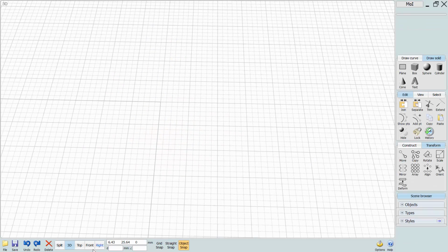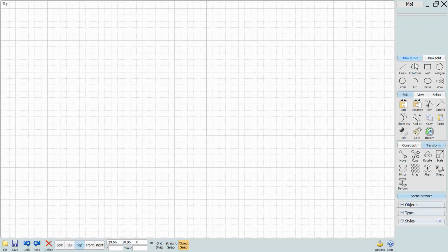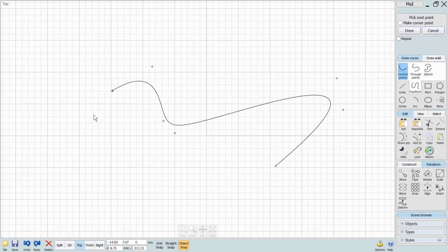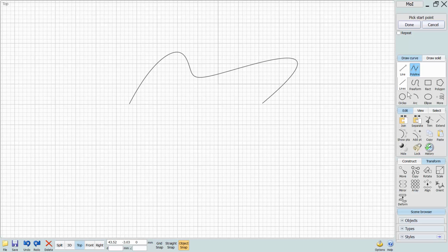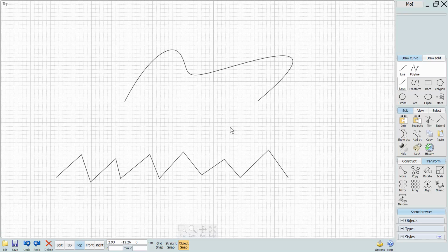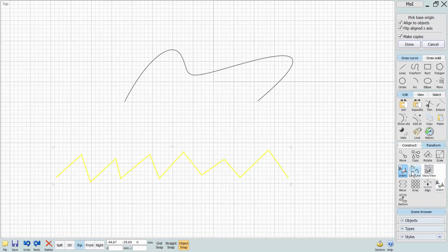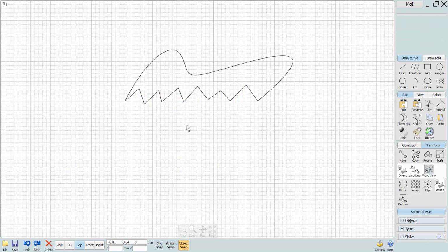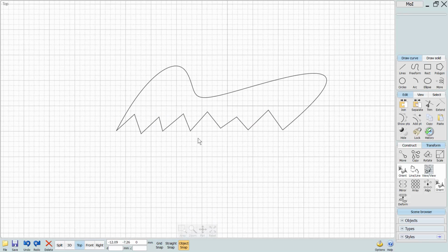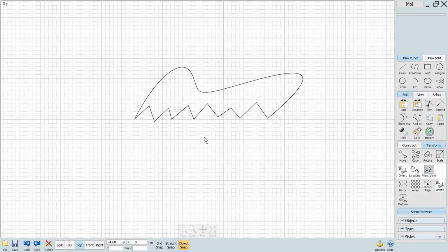With the second one, which is called line, you can orient your elements between 2 points. So let's say you have this curve here, and I want to use one polyline like this. So if you want to fill this gap between this and this endpoint with this polyline, you can select it and then go to orient, and then you can use this line command. And now you need to click on this start and this endpoint, and now you can click here and here, and Moi will fit this into this gap perfectly, and also it will scale this line uniformly.